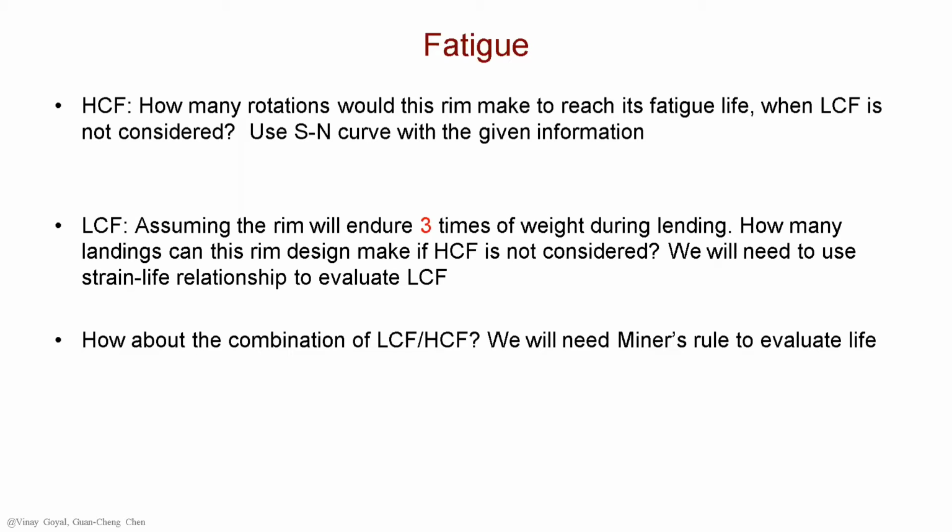So assume LCF, low cycle fatigue, is not considered. You can use the SN curve for that. For low cycle fatigue, we can look at how long this wheel will endure the landing and how many landings can this rim take if the high cycle fatigue is not considered.